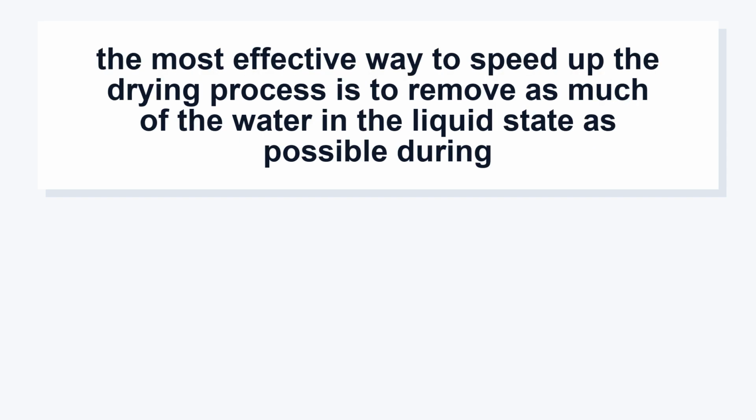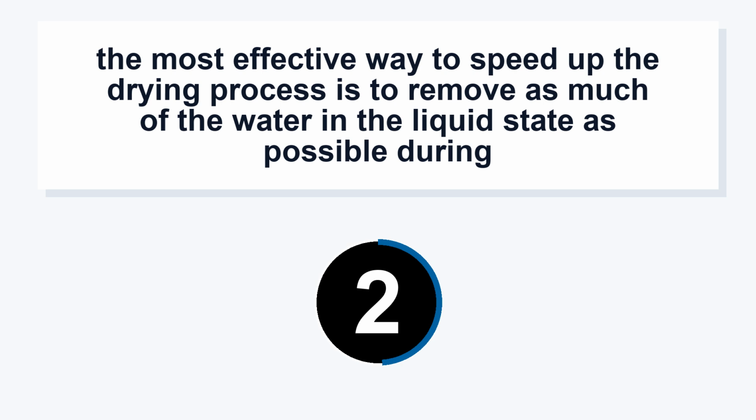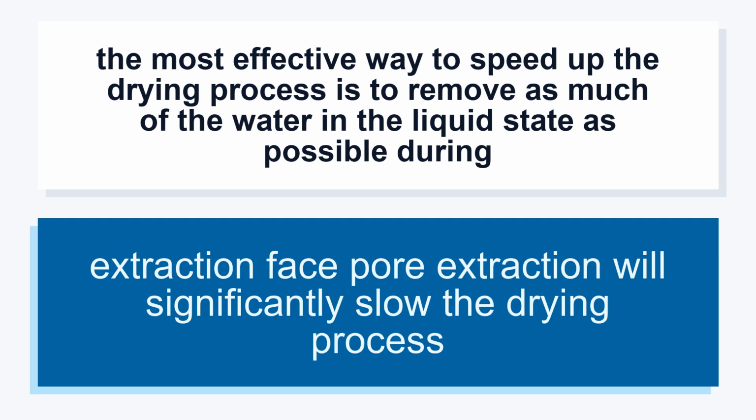The most effective way to speed up the drying process is to remove as much of the water in the liquid state as possible during the extraction phase. Poor extraction will significantly slow the drying process.